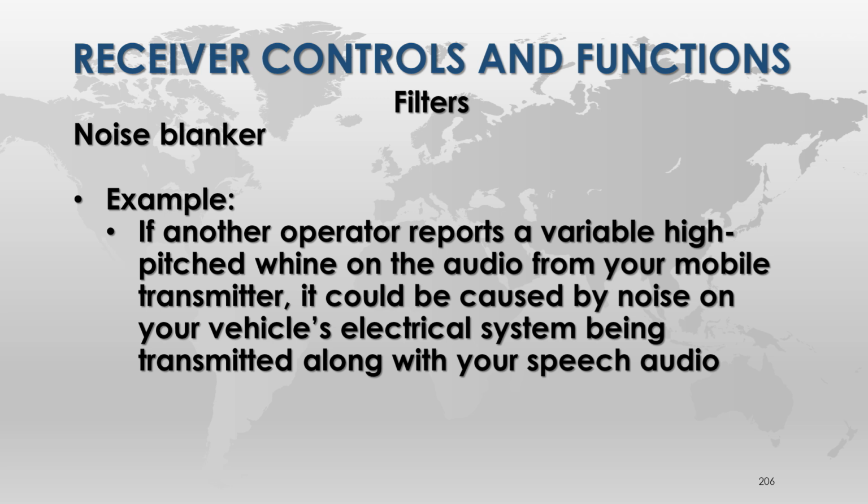Now, what would give you a variable high-pitched whine in a car? Your heater motor. No, really, that runs at a constant speed. It's going to be variable. He's talking about when you hit the gas and you're accelerating. Oh, the frequency of the noise is going up. That tells me that it's something in your ignition system or the alternator. Yeah, the alternator speeds up when you speed up. Your heater can do it, but it's not going to vary. It'll be a constant noise, only if you change the switch position for the fan speed.